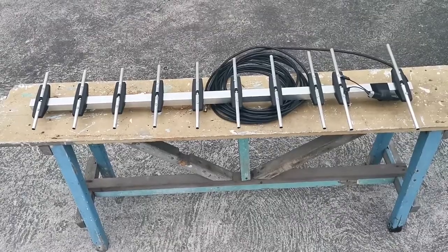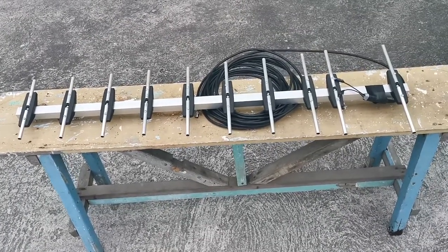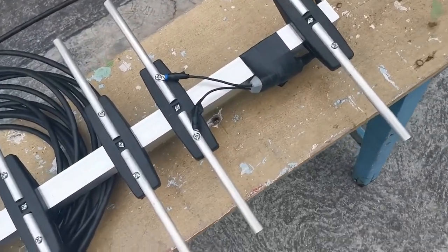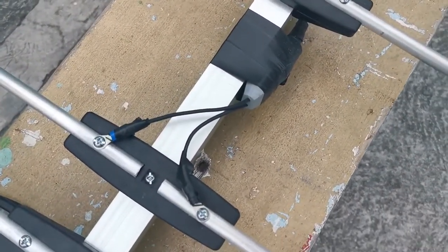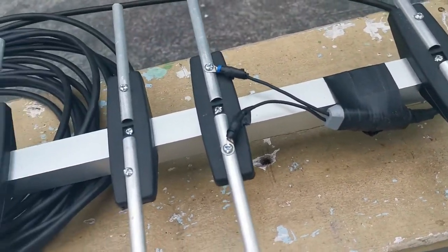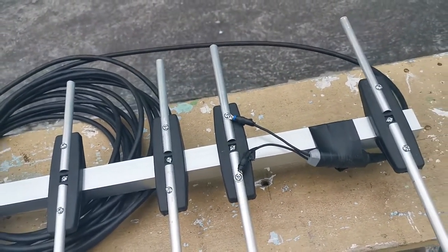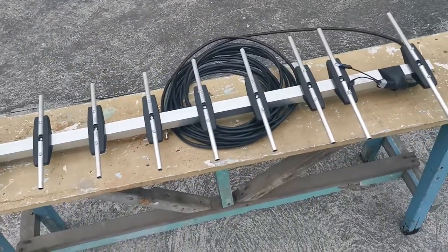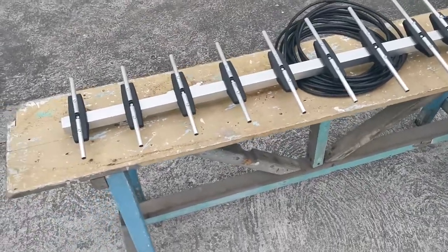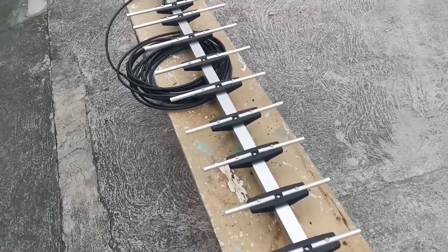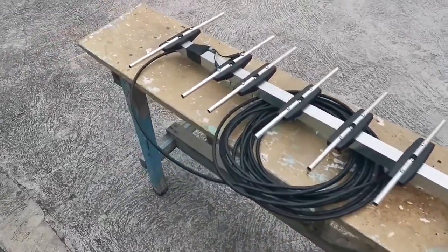Yagi Uda antenna has two basic elements, which are the active and the parasitic element. The active element is an aluminum rod, called a dipole, that acts as a feeding point of the signal and is connected to a transformer that converts unbalanced to balanced signal, known as a balun. On the other hand, the parasitic element is an array of aluminum rods that act as a guide in increasing radiation indirectly.